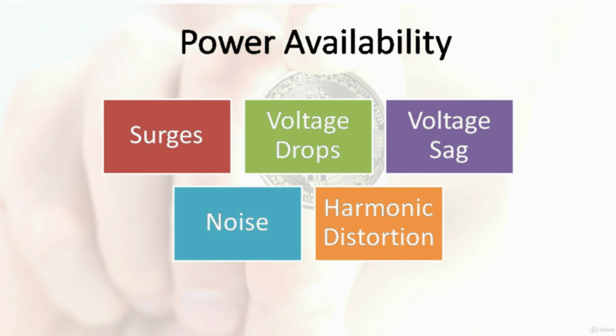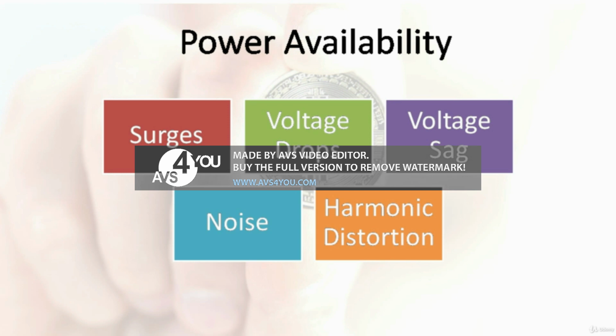A UPS differs from an auxiliary or emergency power source, or what we call a backup generator, in that by providing energy contained in batteries, supercapacitors, or flywheels, it can provide nearly instantaneous protection from input interruptions. Most uninterruptible power sources have a very limited supply time, only, let's say, a few minutes. Yet this few minutes is enough to launch a standby power source or shut down all of your rigs safely